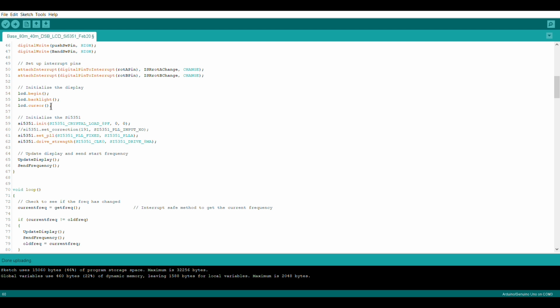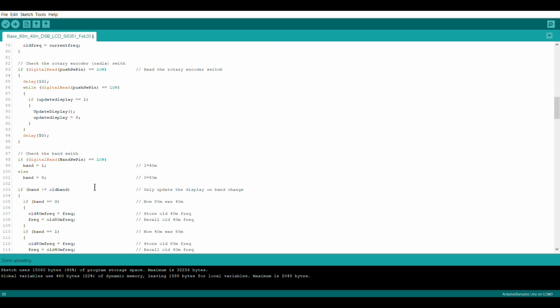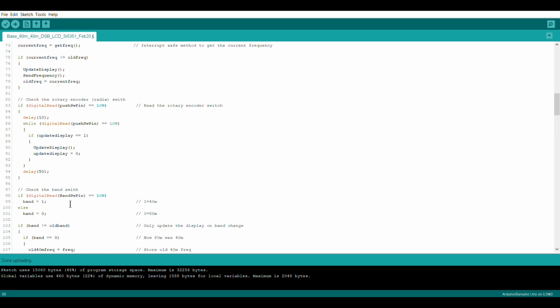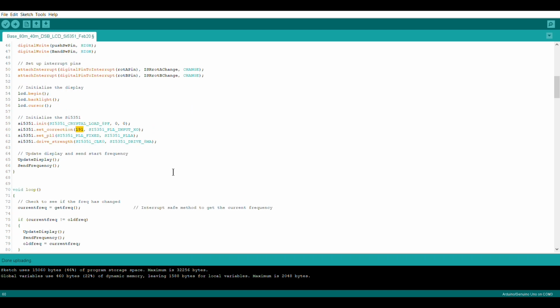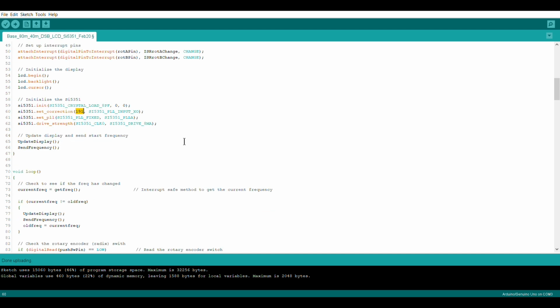But if you want to be smack on, then it certainly is worth calibrating the SI5351, determine what that correction factor is, and then use it in any sketch that you're using for that particular board, noting temperature variations, and potentially, and I don't know this for sure, if I have huge amounts of code down here that are potentially playing around and impacting the I2C, there's other things that could potentially go on. I don't want to say any more about that one because I don't know enough to say any more.